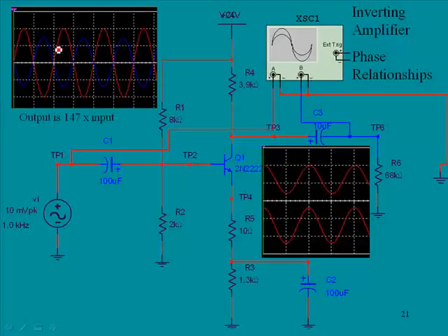Now, there is another type of amplifier configuration called a differential amplifier. We may look at that when we discuss differential amps later. They will utilize two transistors. They usually utilize both a negative and a positive voltage, and the first transistor in that configuration would be the inverting, but the other transistor would represent the non-inverting output. So you could tap the inverting or the non-inverting if it's in a differential configuration.